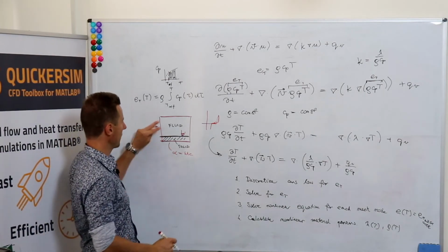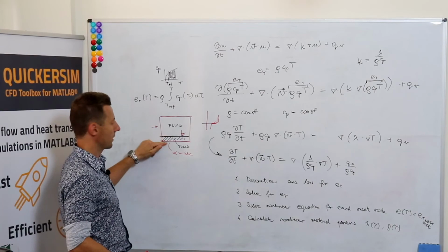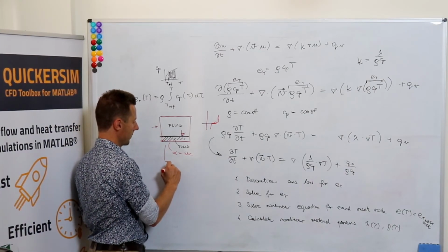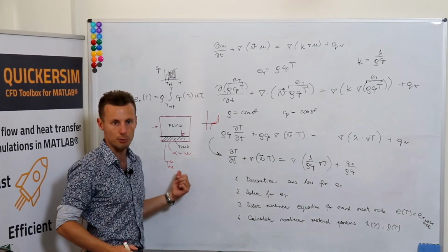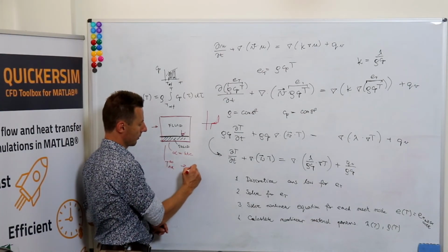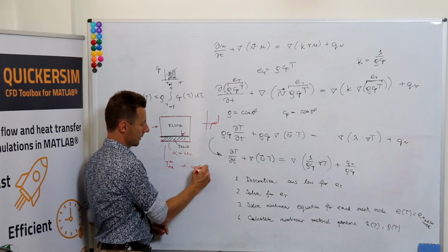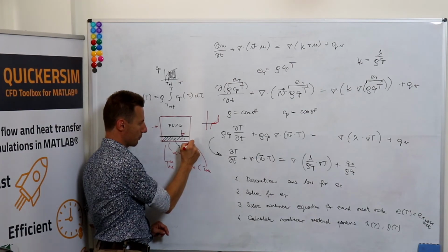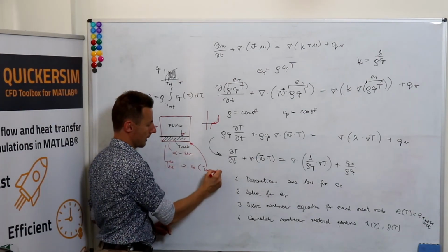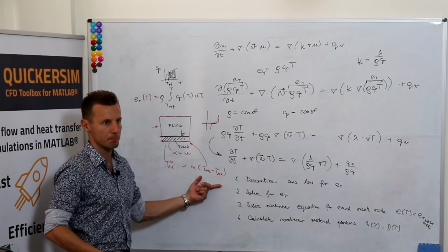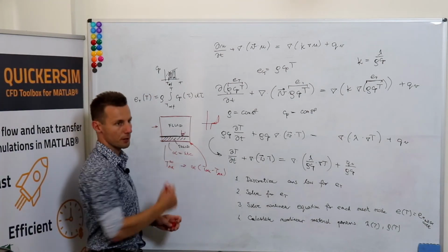If you know that, okay, maybe you've got fluid in your pipe, there's the wall, and maybe you've got some surrounding air, well, in the infinity, so the reference temperature of the surrounding fluid, then you would go again for this alpha times T wall, which would represent the temperature here at that boundary, minus T air. That's perfectly okay, but not at the interface.